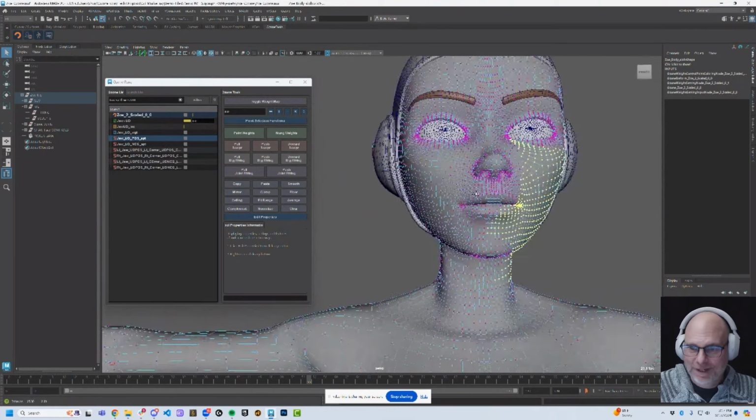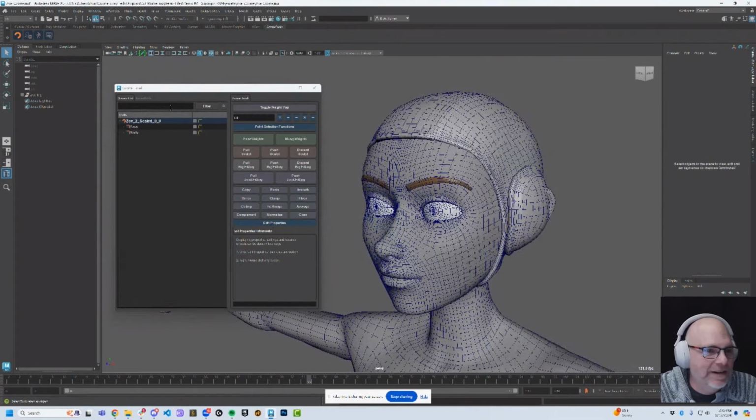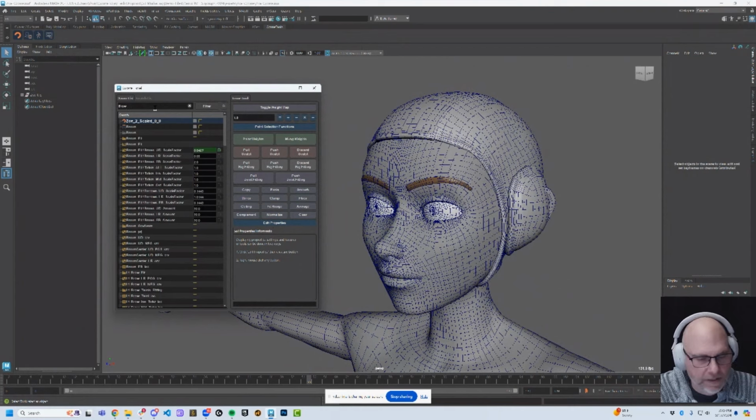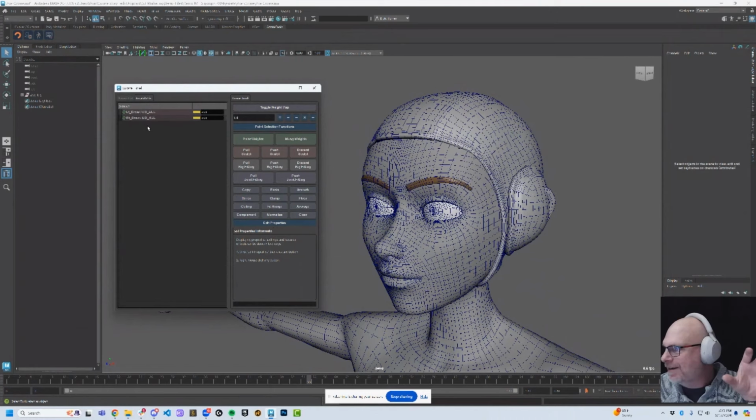Yep. All right. So let me show you the brow, which is another thing here. So let's go and let's do brow. And I'll do -A and we'll do UD to show me the up and downs. So what I'm going to do is I'm going to grab these and I'm going to put them into our scratch panel. So you can see how I can filter this list and kind of look through stuff. But sometimes you want to just focus on the handful of avars and controls you want to work with at a time. So if I right click here and I add to scratch panel, it'll basically allow me to take a subset of the master list and put it into this working space.